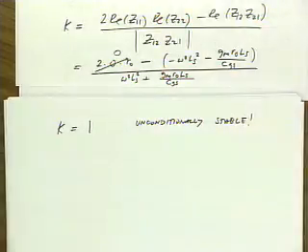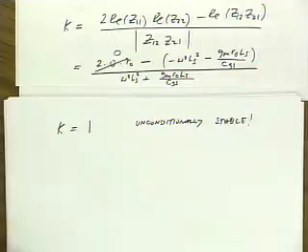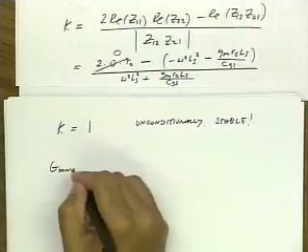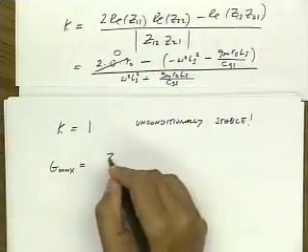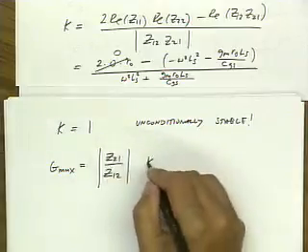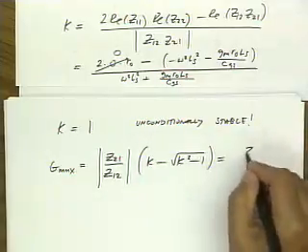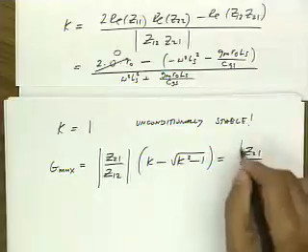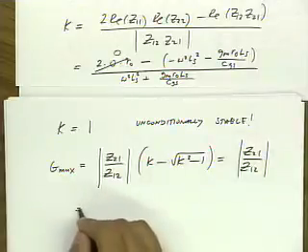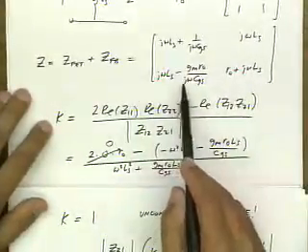That's actually pretty nice. It took our device, which was already unconditionally stable. We introduced feedback, but we found that this feedback could never make it actually oscillate. It's always going to be stable. So now if we look at the expression for the maximum gain we can get from this device, using Z parameters, it's Z21 over Z12, K minus square root of K squared minus 1. Well, K is always equal to 1 for this amplifier, so it's just Z21 over Z12.